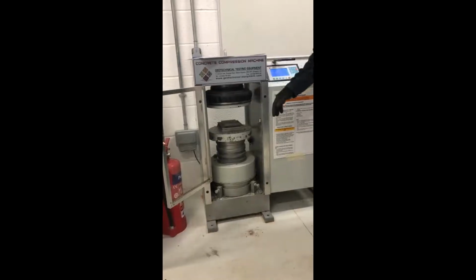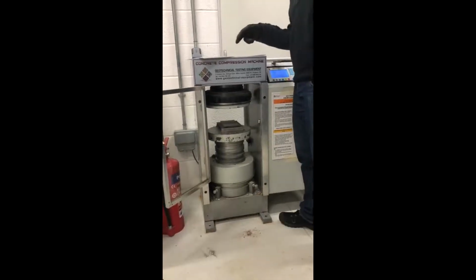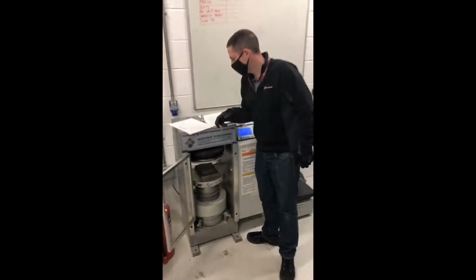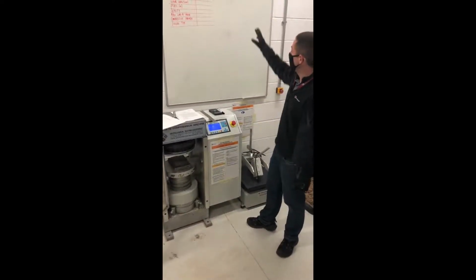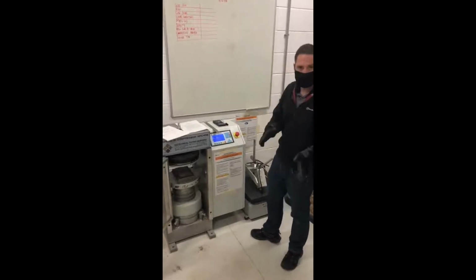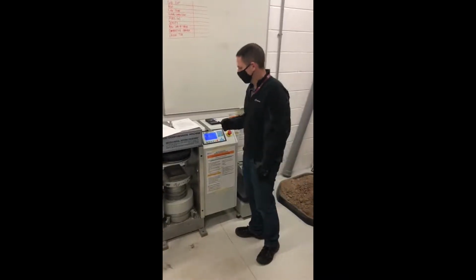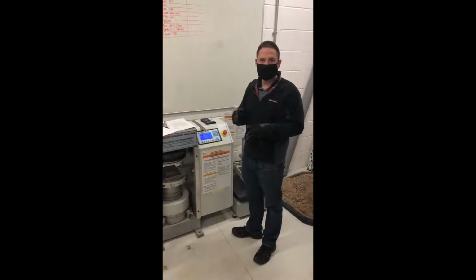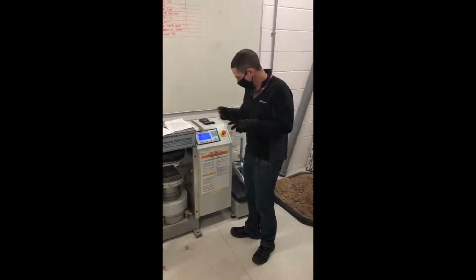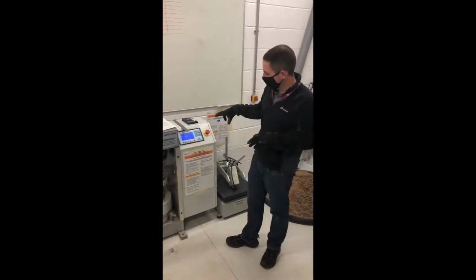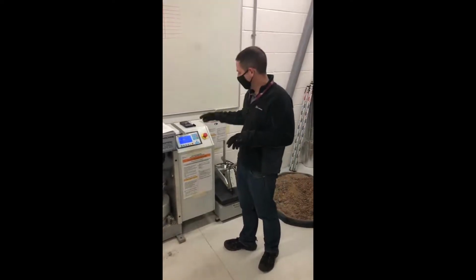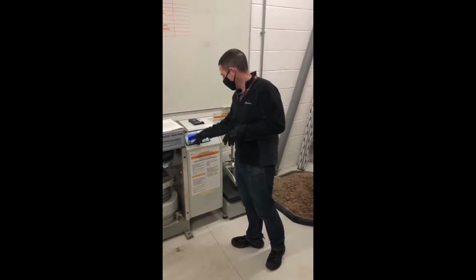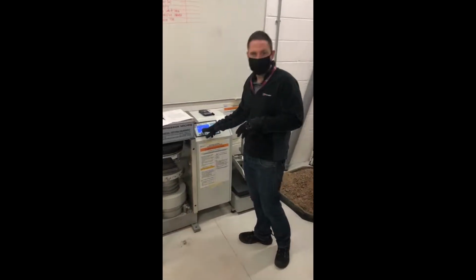In our case, the standard we're going to be referring to is BS 12390. This dictates that the cubes we're going to be looking at should be about 100mm by 100mm in plan. For that particular cube size, as defined in British standards, there's a pace rate of 6 kilonewtons per second.